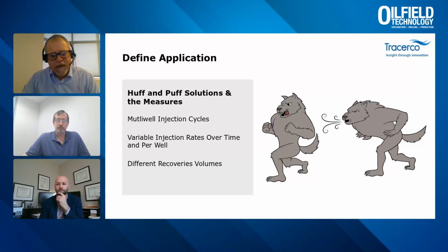So what we're facing now in comparison to an unconventional completion is that there are multiple wells being injected into over periods of time at different pressures and different rates to create an environment that produces more oil out of parent wells or fully developed fields, areas where secondary recovery in an unconventional may have some economic viability.